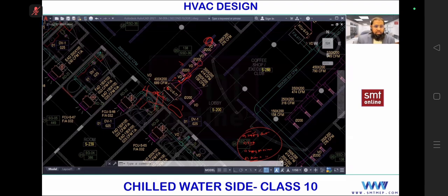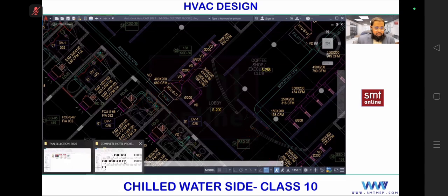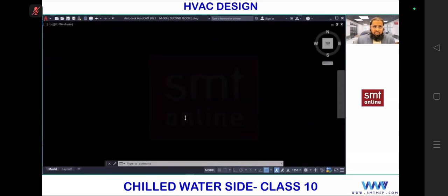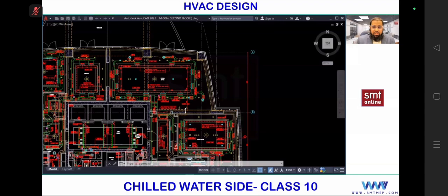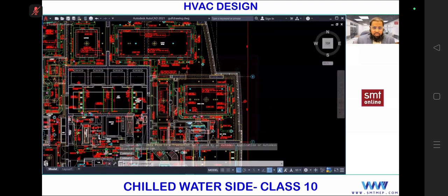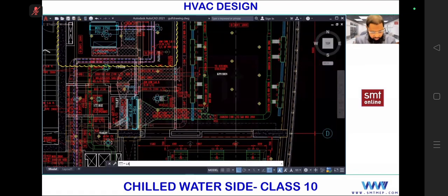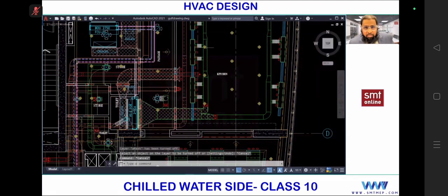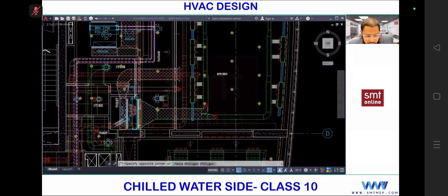So for this let me open one drawing, the same previous drawing, the toilet area supply plus return. Second case you can write AHU with supply plus return duct. Now in this example you see, I think you know this example, the kitchen area we used at the starting sessions layout. Now in this case let me explain first. For selecting the fan for this unit, FC or AHU, we need to consider this supply duct. Again supply duct means the critical path. Then these fittings and accessories like VCDs.